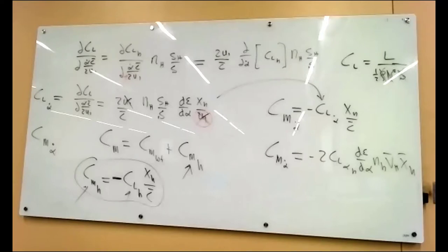I mean, you'll be a technical engineer guy. And you'll impress him if you can give him an explanation that doesn't include 2 pages of equations, right? So what would you say? Go back to the fundamental explanation that I said, is that this is an effect of the time it takes the wake vortex to get back to the tail. And that's why we get the time dependence on angle of attack, right? So that's the explanation that you'd say.